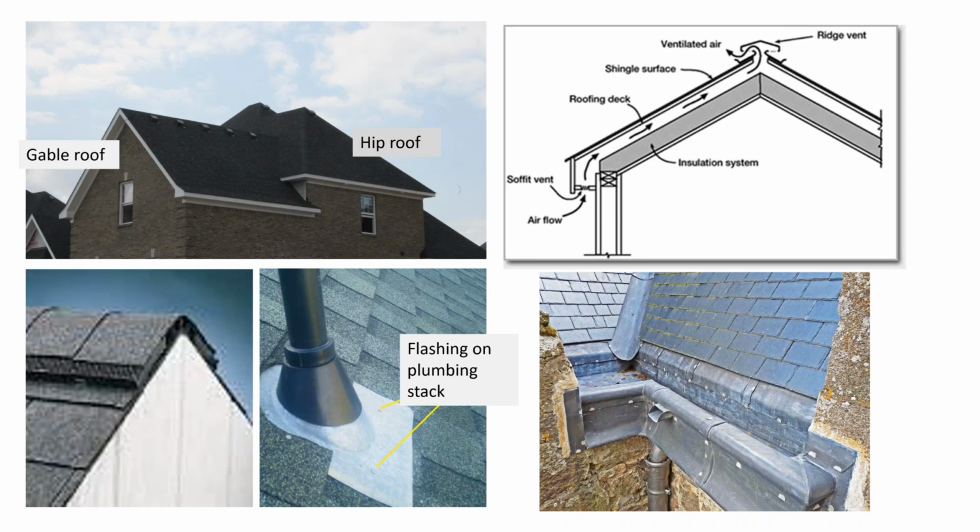I don't know why. But if you have a flashing problem on a plumbing stack, that's what this is. All plumbing drains require ventilation. You have to have air in order for the drains to work. So this typically will let you know that it's either a kitchen or a bathroom above this, because this is going to be the vent stack for your plumbing.